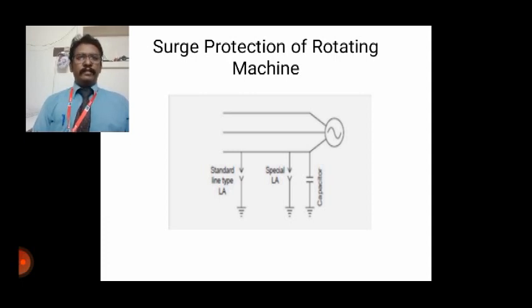For analytical purposes, for the machine it is 15 to 20 meters per microsecond. This means that in case of surges with a steep front, the voltage will be concentrated at the first few turns. Since the insulation is not immersed in oil, its impulse ratio is approximately unity, whereas that of the transformer is more than 2. These points you have to keep in mind.